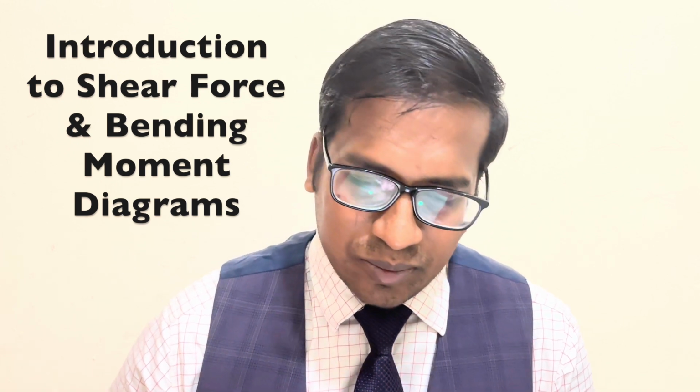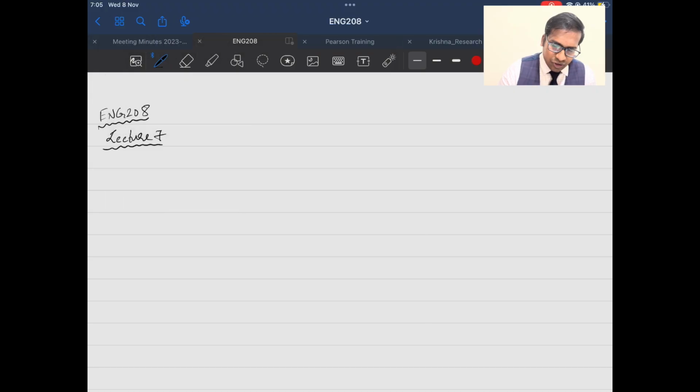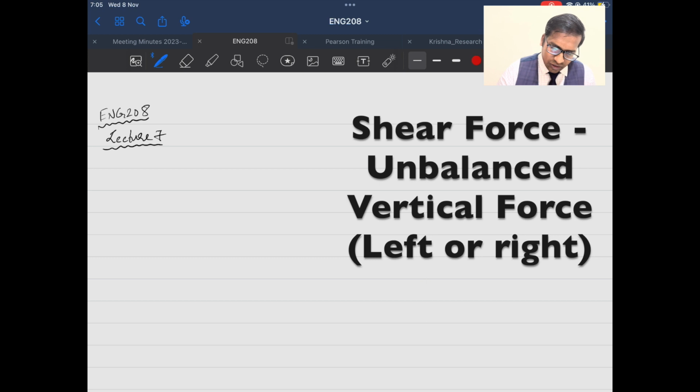Now, in this video lecture, we will be looking into an introduction to shear force and bending moment diagrams. Now, when I say shear force, this refers to unbalanced vertical forces either on the left or right side of the beam.